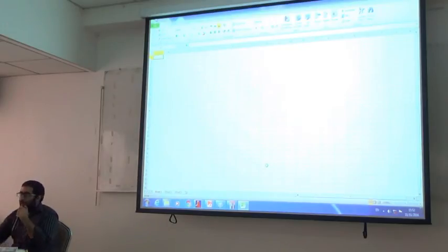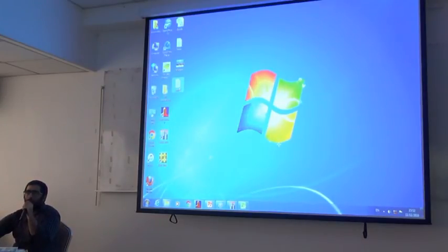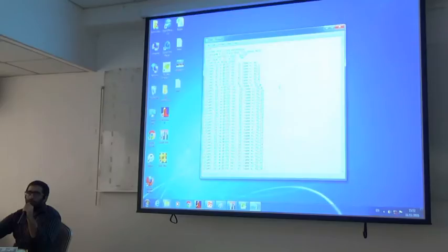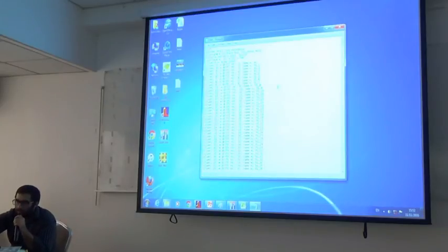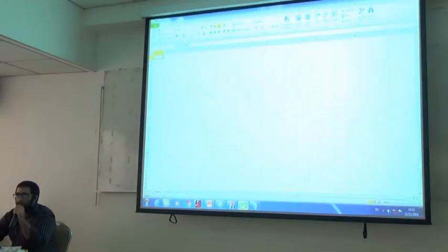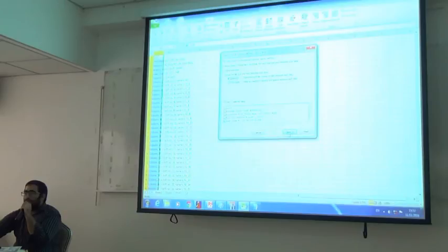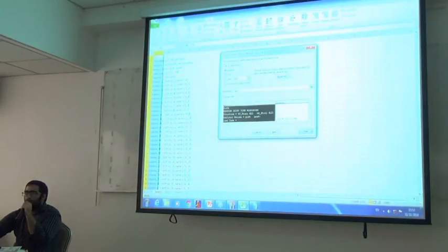Okay, so as I showed you, we already extracted the drift results, and when I extracted the drift results, I used the time history option, right? So now what I will do is copy the data from the drift tab in the drift file and then paste it in Excel just to show you how long the data is if we extract the step-by-step result, right? I will just paste the data in Excel and then use the same option that I used before, text to columns, delimited by comma.